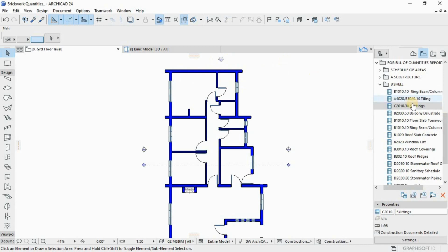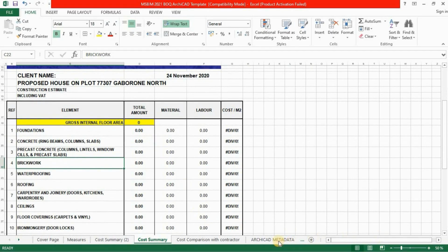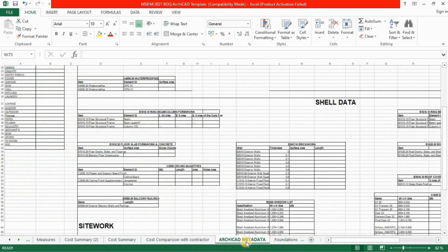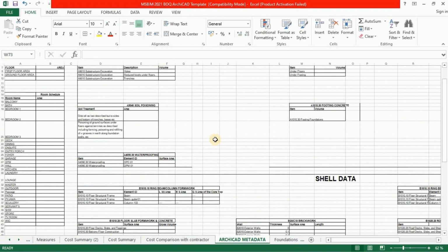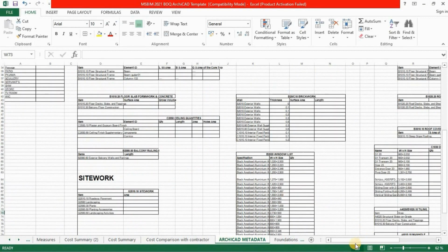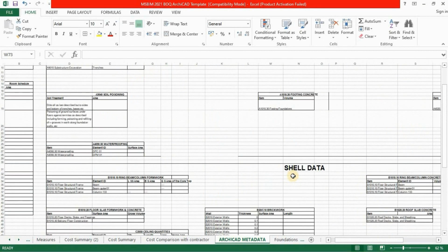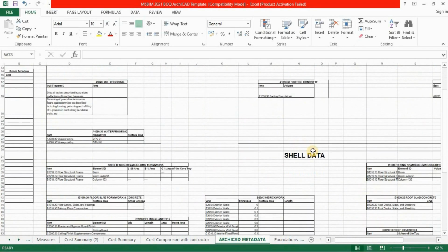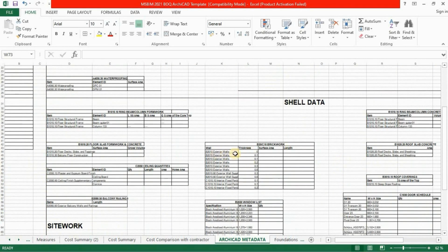We can export the schedules to Excel for further editing, hence enabling collaboration with other AEC consultants. If at all you have a dimension of 5D in an office, this is where they come in. You'd be saving Excel files for them to basically do the quantity takeoffs of the model. That's basically quantifying your model.